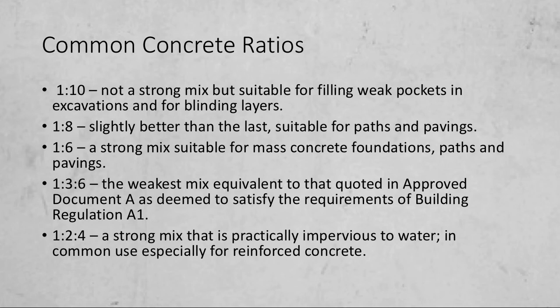1 to 10, and this is not a strong mix, but is suitable for filling weak pockets in excavation or for blinding layers. 1 to 8 is slightly better than the last one, and suitable for paths or paving. 1 to 6, a strong mix suitable for mass concrete foundation, paths and paving. 1 to 3 to 6, the weakest mix, equivalent to that quoted in Approved Document A, and this is a set of building regulation documents